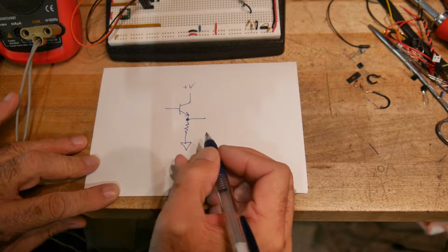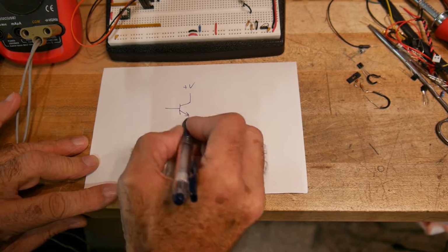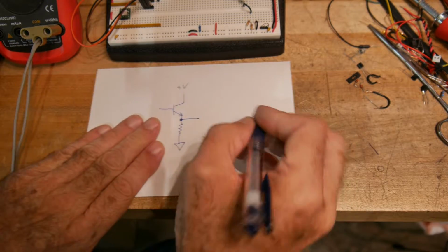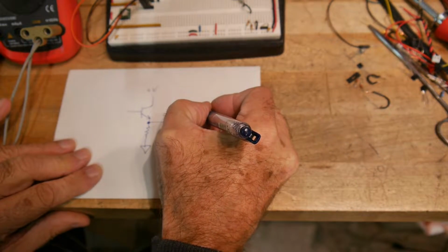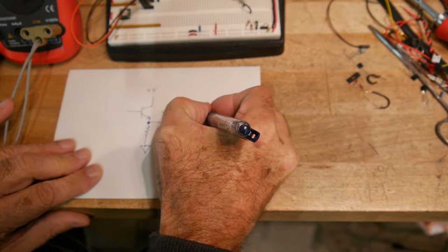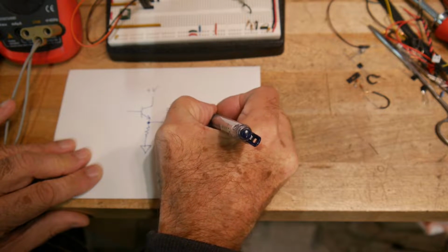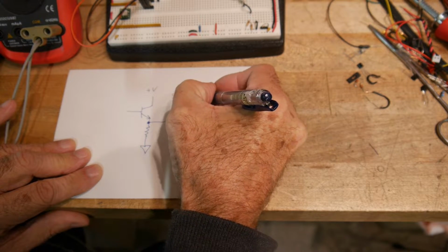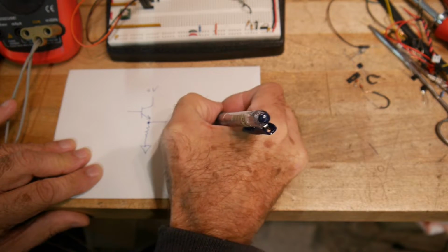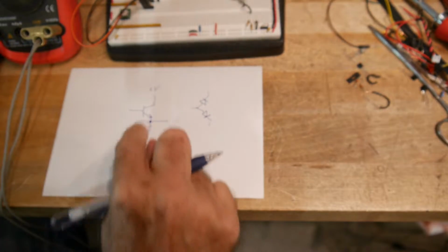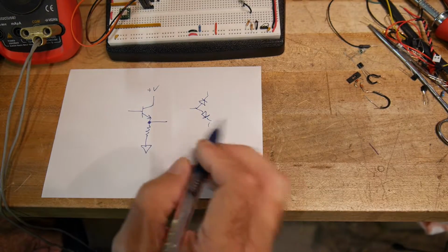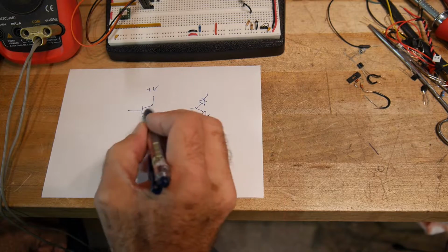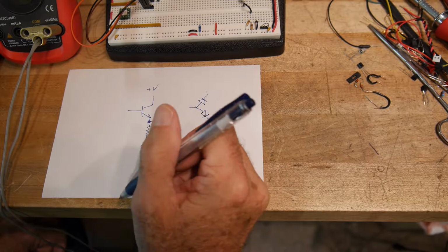we had a voltage drop across the diode, right? So this transistor looks like 2 diodes. It looks like one diode in this direction and a diode in this direction. And that's the way you can test these transistors also, is you can use a voltmeter and make sure these 2 diodes are still okay.